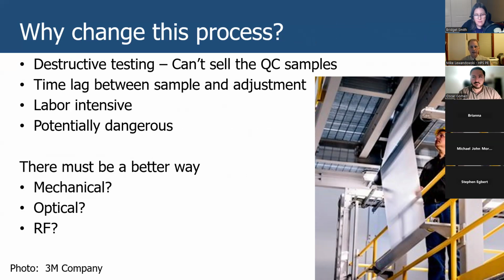The other thing to think about is that there's a big time lag between when you take the samples and when you get the results. So think about this. You walk out to the manufacturing line, you cut your sample. You walk back to the laboratory, make your measurements, do your calculations, compare it to your tolerances, go back out to the coating line, and you tell the person that's operating the coating line what adjustments they need to make to the equipment.